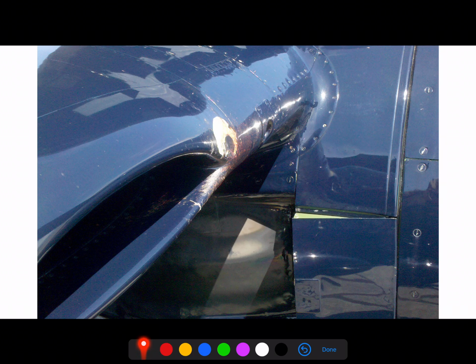So what we're looking at here is a Tiger Cat. We have an engine nacelle over here with a Pratt & Whitney R2800 inside, and the fuselage is over on this side. And this large scalloped opening right here is where the oil cooler lives. The oil cooler is actually recessed just a bit in here, but this ducting helps to force ram air from the outside into that oil cooler. And then there are doors on the back that can regulate how much air is flowing through.